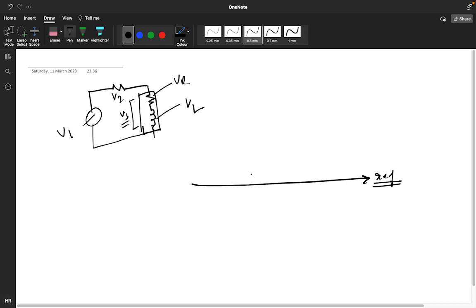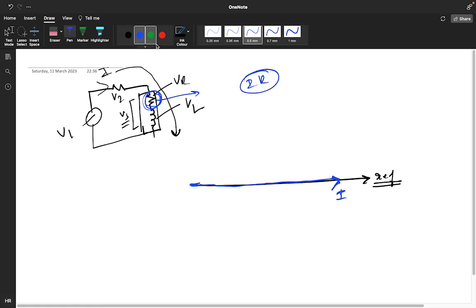So if you are drawing for this V3 network, because the current will flow the same in this circuit, correct, Prasanna? Same current will flow. I am assuming the current has been taken as a 0 degree angle. Okay, I am just assuming, nothing is given. So this is my I. If I multiply it with this particular resistance R, I into R, you will get VR value, right, Prasanna?